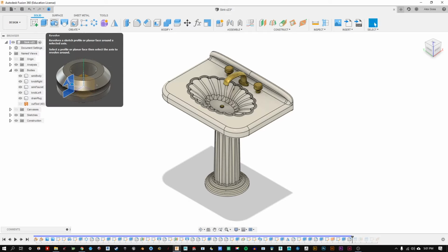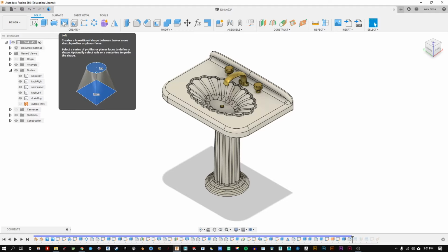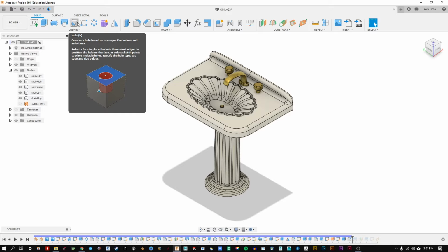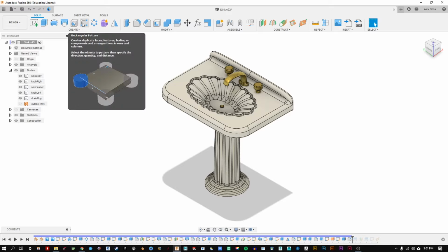I think these pictures are great. It's one of the reasons I really like Fusion for people who are learning for the first time. There is so much vocabulary involved with CAD that not only learning the words, but learning the things that you need in order to accomplish that task or that command. So for example, Loft is one of those tools that can be so powerful and fun and exciting, but if you don't know that you need 2 or more sketch profiles in order to loft something, it can be really frustrating to get started. So this little graphic, I think, shows this really nicely of what goes into it. And it's all drawn in the same kind of Fusion interface, so things should look familiar. Okay, just going through these.